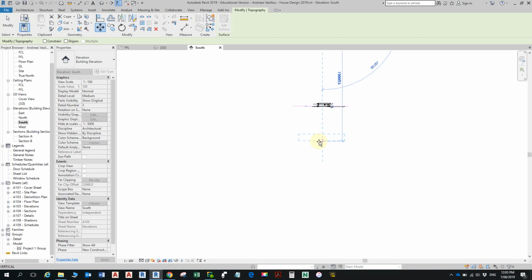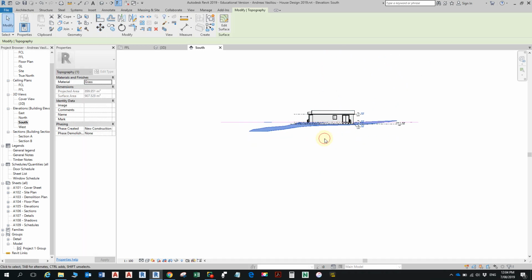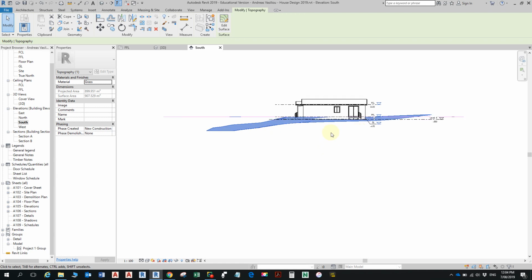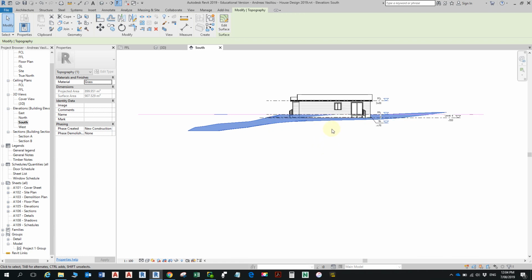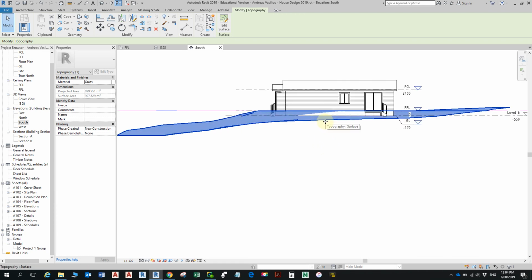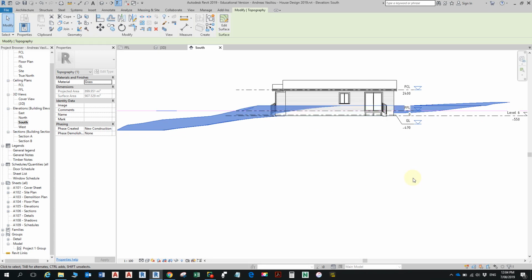All right. So to avoid that, there's a couple of things you can do. But what I'm going to do is actually make sure I'm not near anything that I'm going to click to, the endpoint of something or midpoint, just away from anything like here, and that sort of puts it in the right spot almost as well. And if you want to do some final adjustments, it's highlighted now. You can use your up arrow, for example, and down arrow to get it in the right spot.